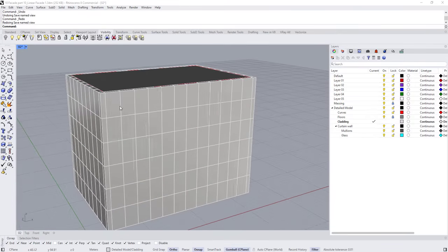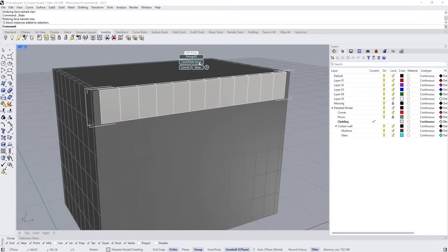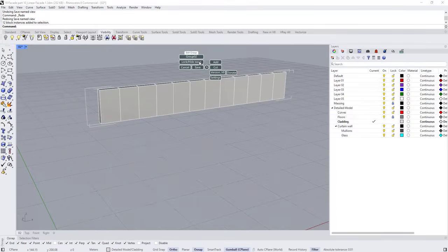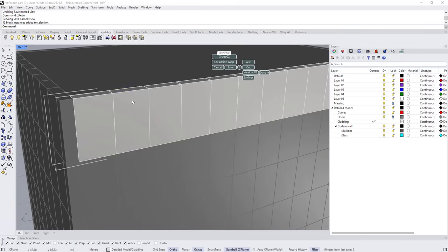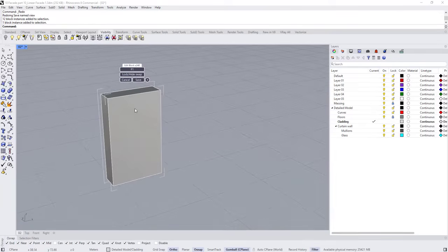Okay, now let's start adding detail to one of these blocks. So double click on this group. I'm using a plugin called Block Edit New. It adds a lot of features like isolate, and it allows you to edit non-uniform sketch blocks and a lot of other stuff. I already created a tutorial about it. You can check it. It's called Block Edit New, and you can download it. It's for free. So now I'm going to edit one of these blocks. So let's isolate it and let's start adding details.